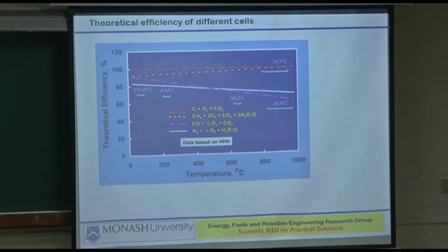But if it is not clean hydrogen, and it also has ammonia or hydrogen sulfide inside it, that means your gas cleanup system becomes a lot more critical for fuel cell application. In the presence of those pollutants in the hydrogen gas going into the fuel cell, the electrolyte will gradually get degraded.